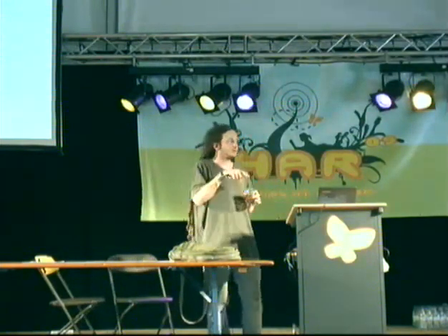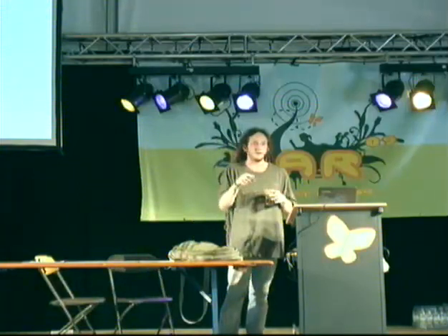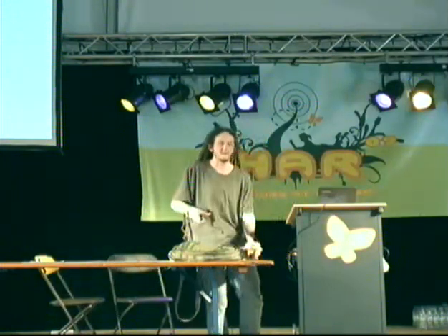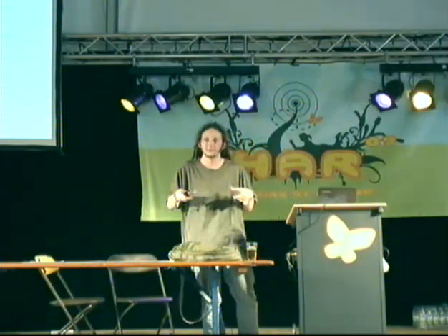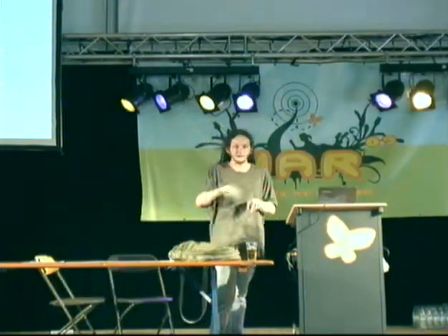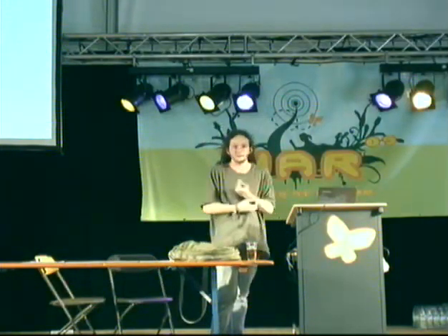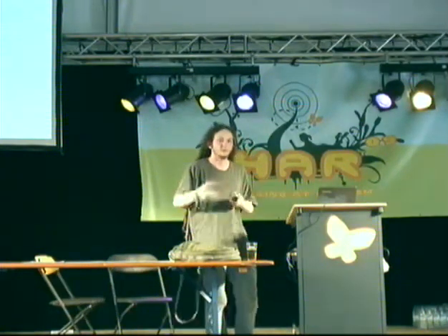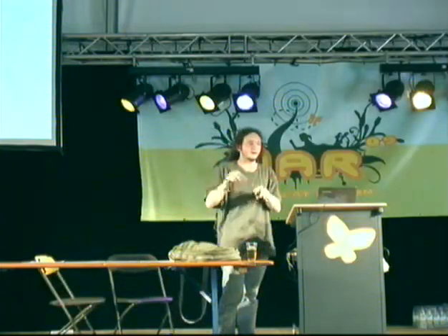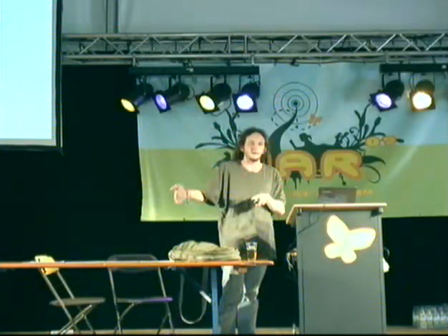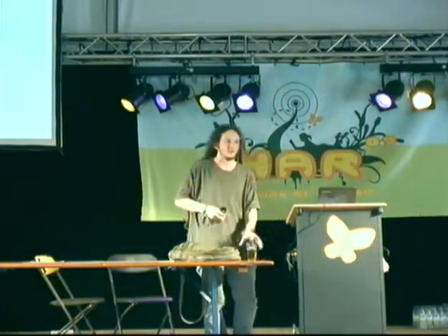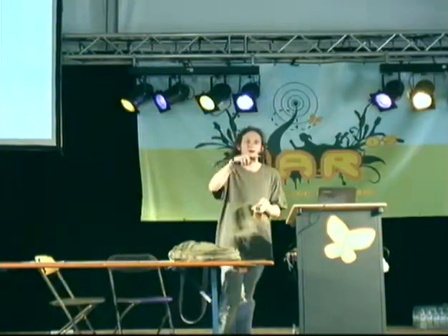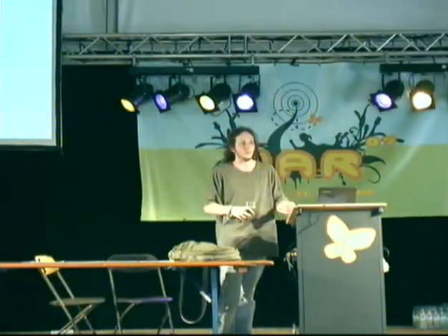On each one of these, if you can mess with the value that gets latched in, you can fall into a random state. And in the case of JTAG, you've got a map that they actually give you as part of the standard. And if you look at this map and you pick any random location, you might land in the state where you are loading a word into the instruction register. You can always navigate from there back to the beginning by sending the right sequence of bits on the right input pins. So all you do is jump ahead of the fuse check and then navigate your way backward to the beginning where your debugger will work.